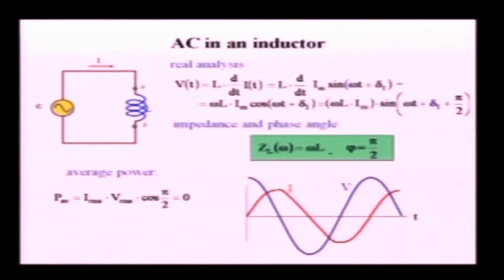It is that in certain fragments, well, actually we can take a look at this. Let's say at this instant, how much power is delivered to an inductor? 0. Now in this interval, power delivered to the inductor is positive, negative, or 0? Positive, yeah, because both current and voltage are positive.